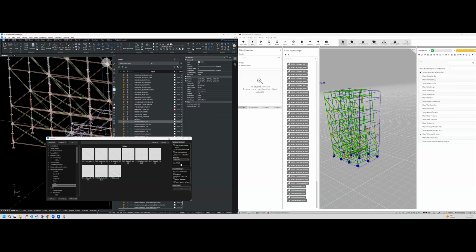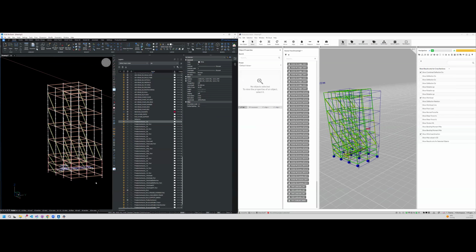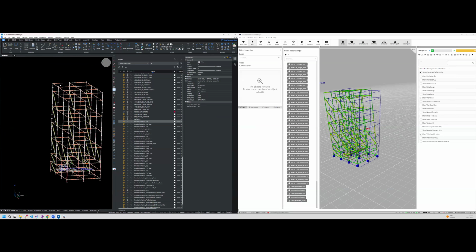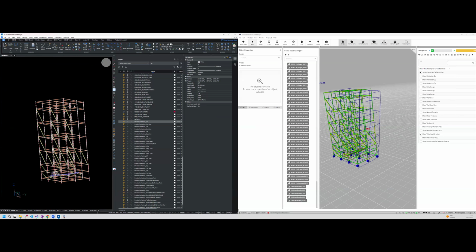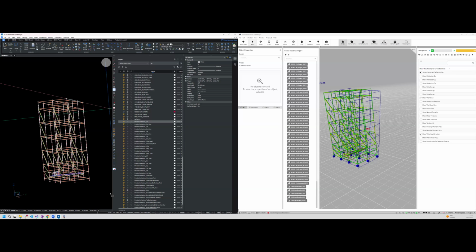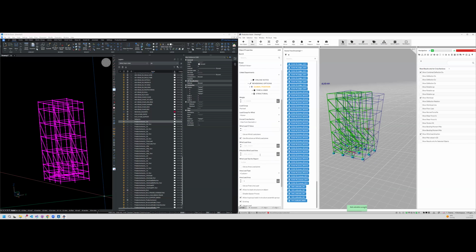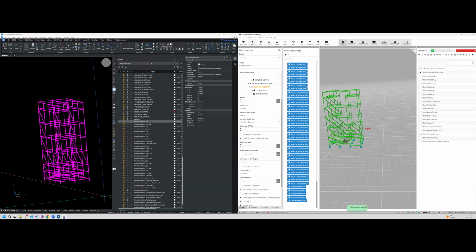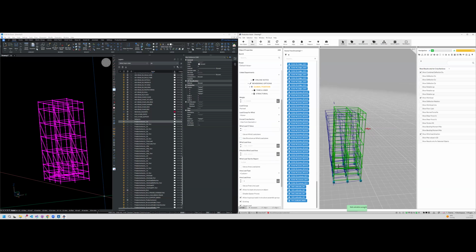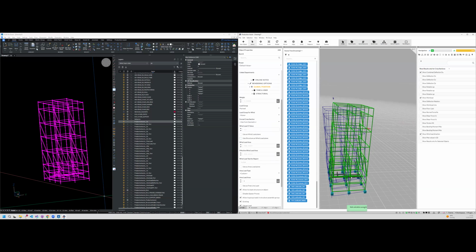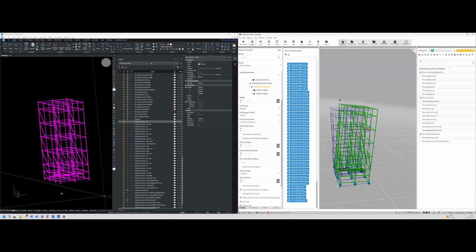There are two more things that I want to show you. One is the wind load integration for planes. Currently, when you're doing it like this, basically only the tubes actually generate wind load. But that is not always what you want. So I will disable this, and you see the deflection goes away again. Because it's a little bit heavier on this side, it will only go in this direction.